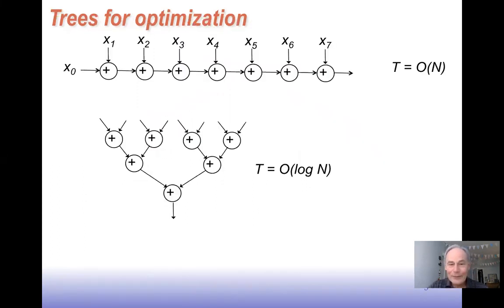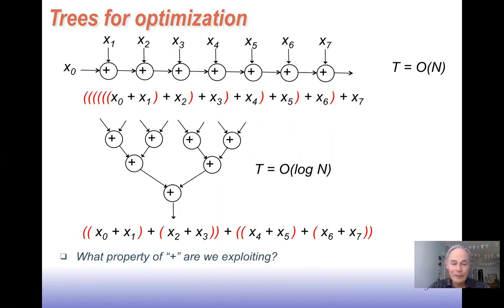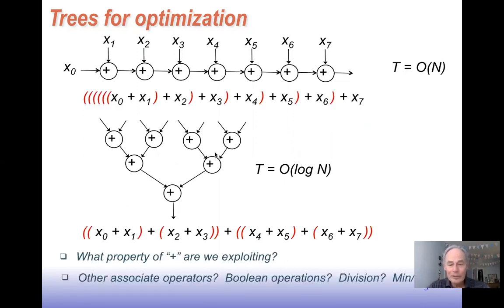All right, so we talked about different types of trees, and when we talk about trees, we're really looking for ones that are good for delay. We really are looking for balanced trees, as shown in the middle, because even though the top tree has the same number of nodes as the middle tree, the top tree has a delay proportional to n, whereas the balanced binary tree has a delay of order log n.